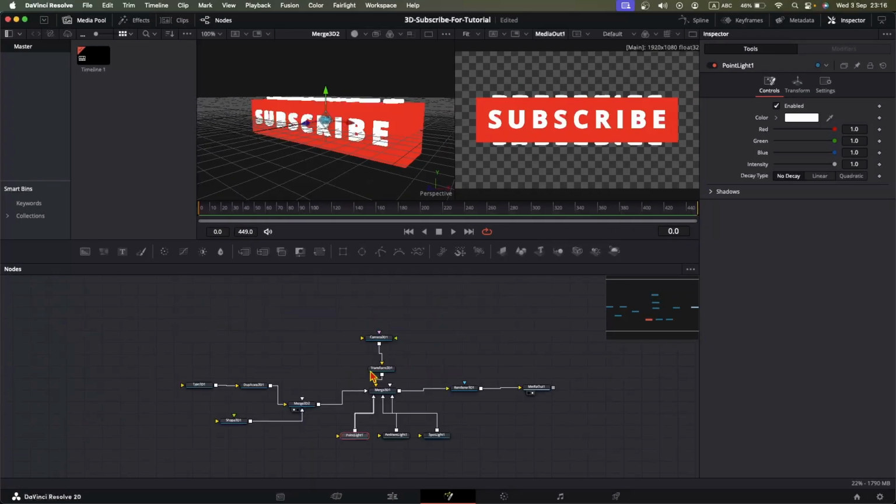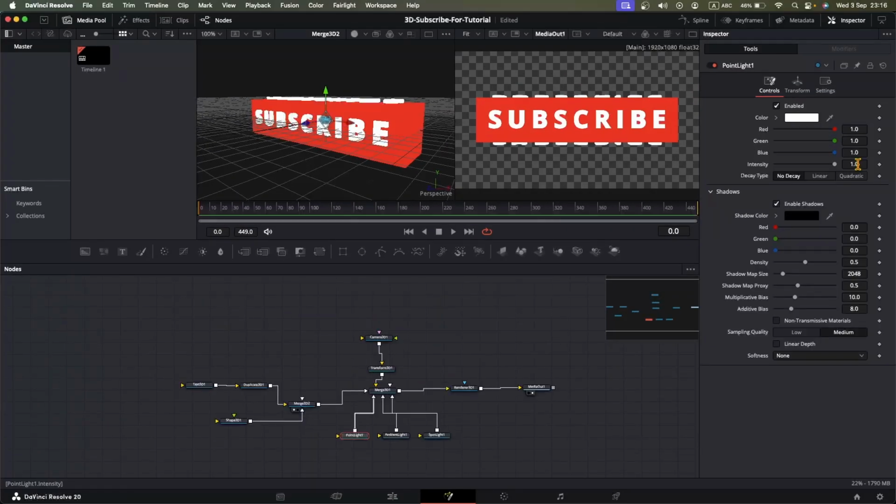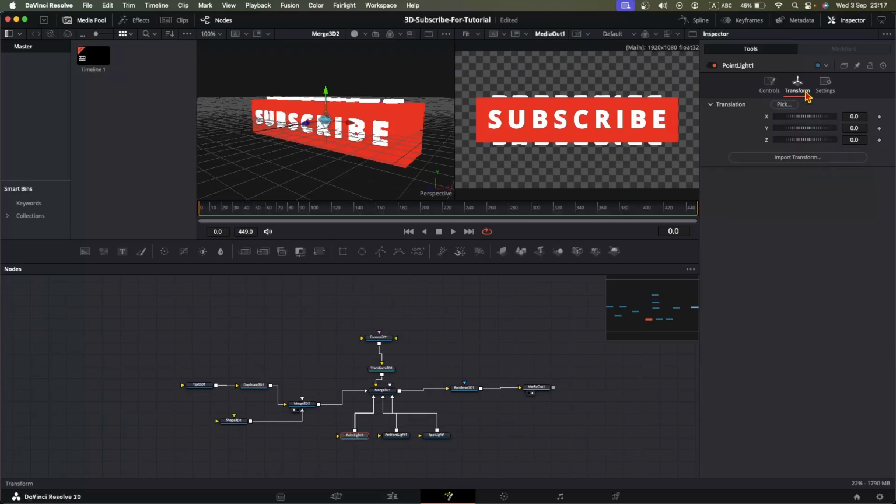Now let's change some settings for the point light. Just change the intensity to 0.71. Put minus 0.087 for the X. And for the Z translation, 0.43. Now we move to the ambient light, change the intensity to 0.535